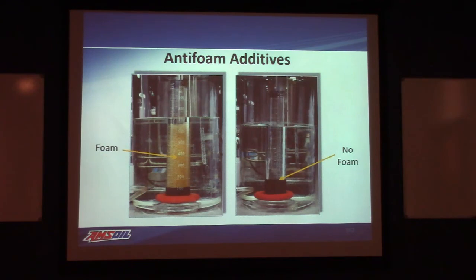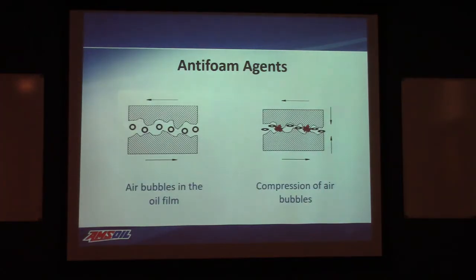And it's not good for a couple of reasons. The first one: we use an oil or a fluid because of its non-compressibility characteristic, right? You put the oil film between two components, it's non-compressible. Theoretically, those two components should never touch. Now suspend air within that oil film. Air is compressible.